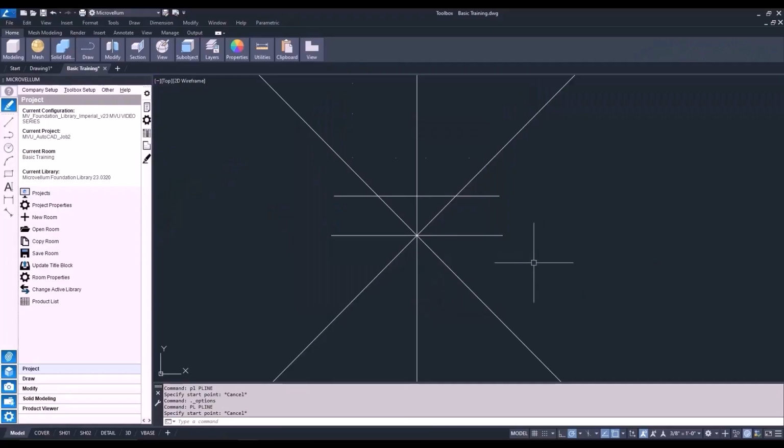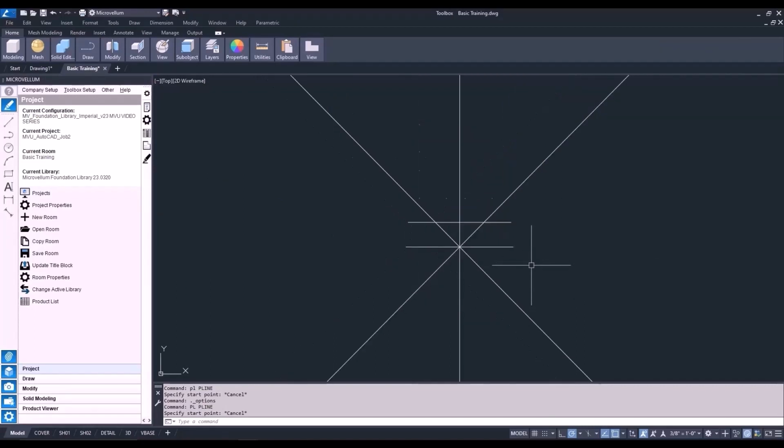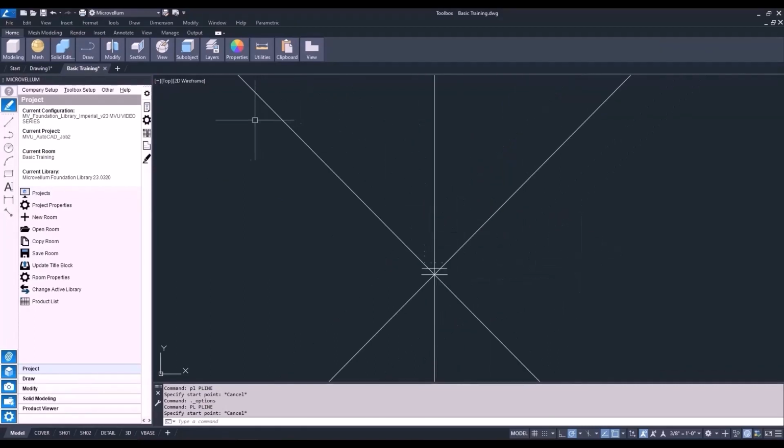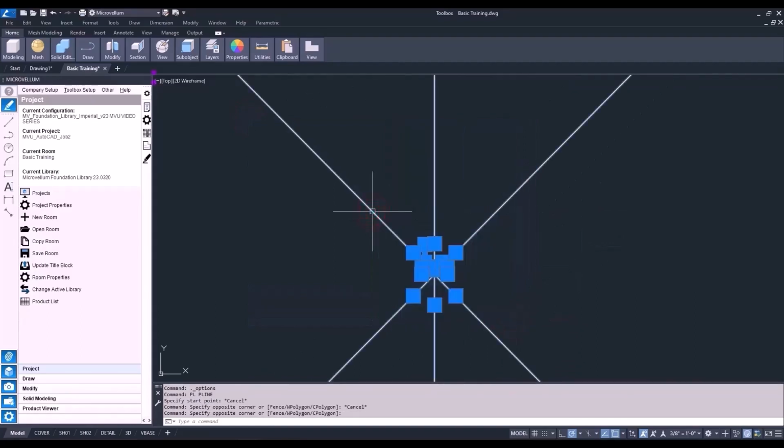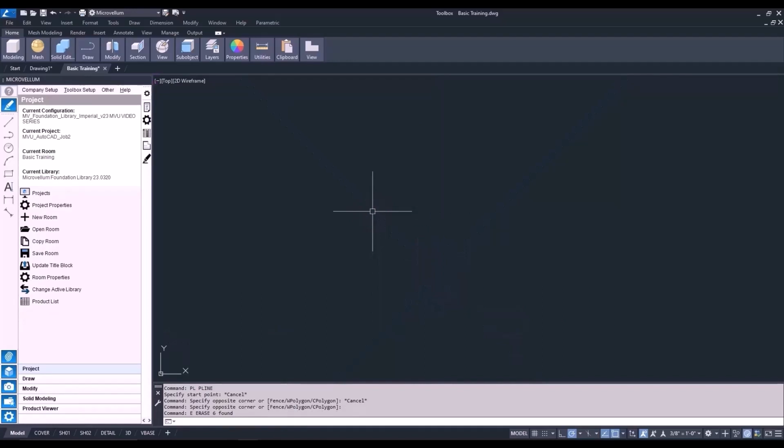So now let's get rid of these things on our screen and start with this drawing exercise. So select your objects. You can see from left to right isn't going to work because we have those construction lines. So we're going to have to use a window from right to left, or just select those objects, and you can hit delete on the keyboard or type in E for erase, which is the AutoCAD erase command. They both do the same thing. I prefer to use the shortcut commands on the keyboard, so you'll typically hear me say just type in E for an AutoCAD erase.